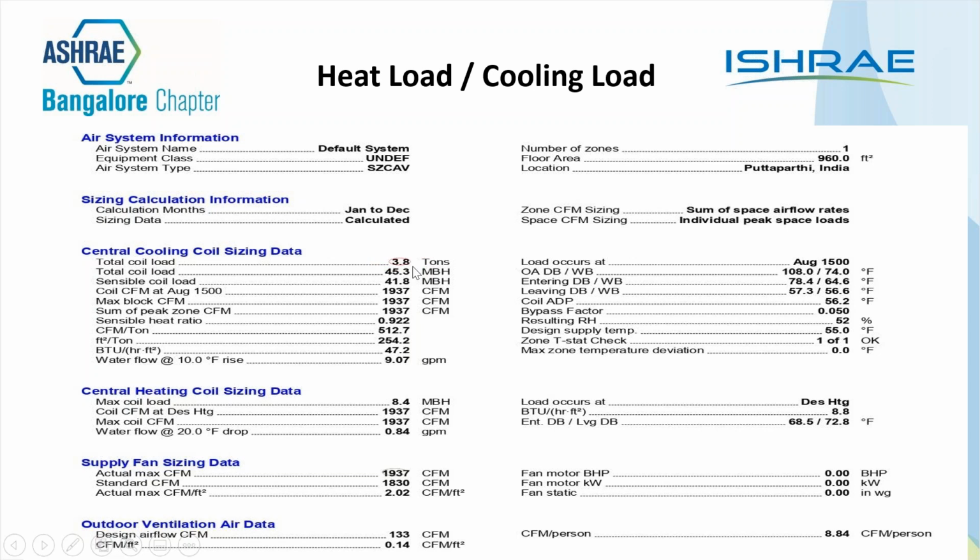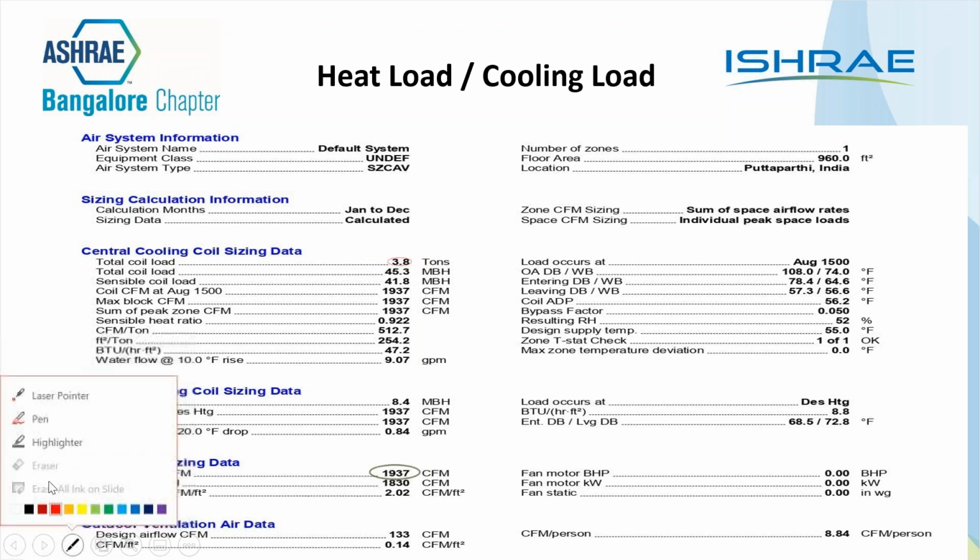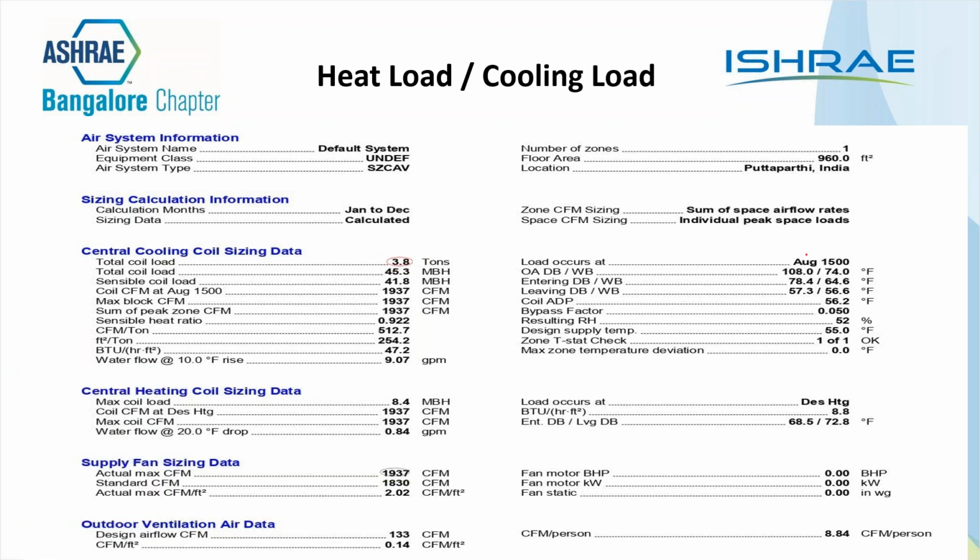If you put, let us say, a 4-ton air conditioning system, and assuming that you are going to have a cassette type of indoor unit, which generally delivers about 300 CFM of air per TR, what happens if you have to achieve this 4-ton? You will get about 1200 CFM of air.